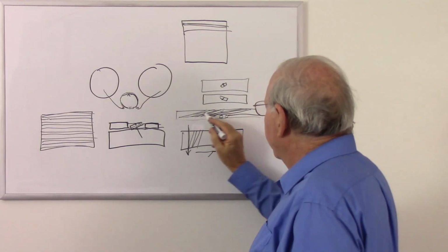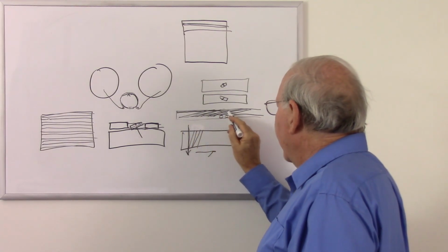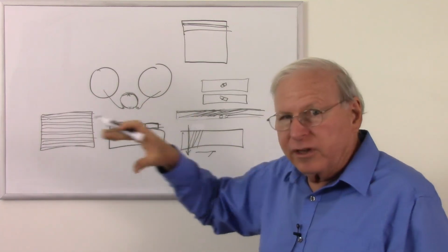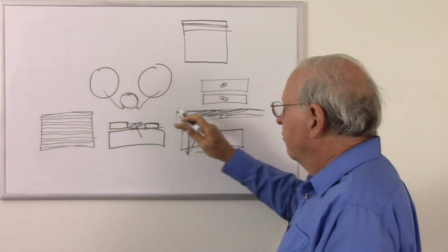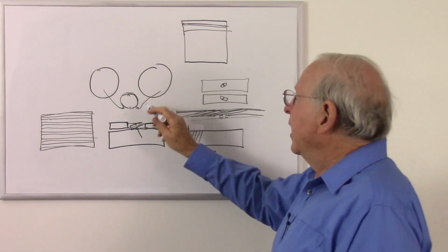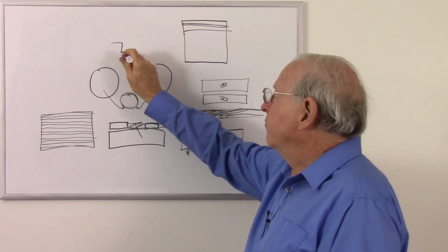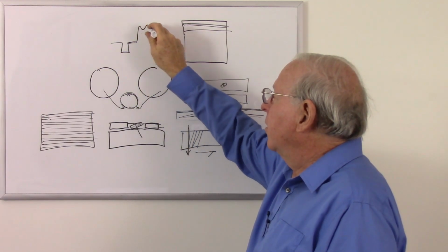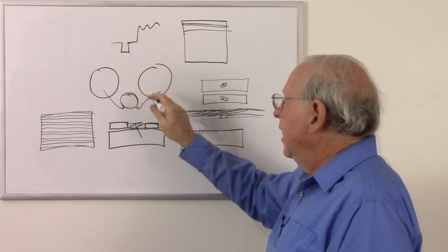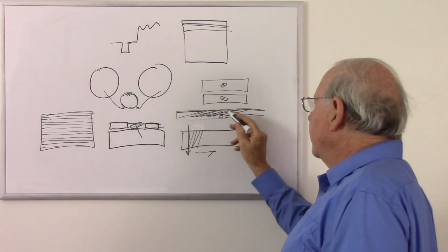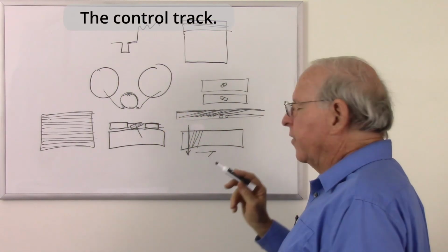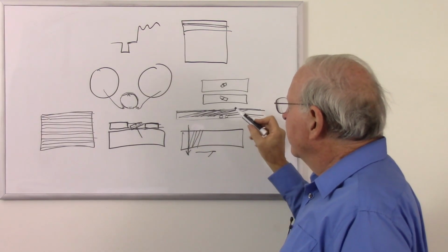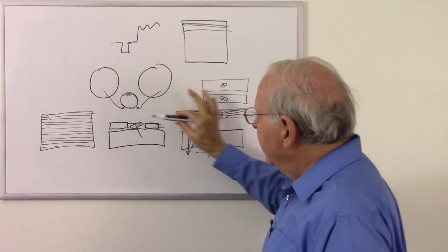And of course it also had a track on the top to give synchronization information to go to the TV circuitry to make everything synchronize with the tape. It did not lay down the synchronization information as far as I know, so that synchronization pulse that comes before, I don't believe that was put on the tape. That was put on the technical information track that was on the other side of the tapes, very similar to the transverse scan. And so that's in a nutshell how the VHS worked.